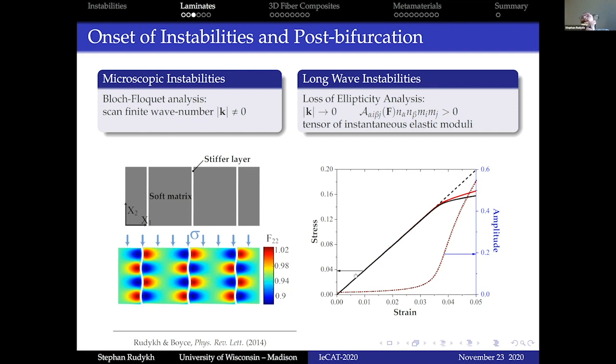and then you can see what happens after the buckling happens, how that develops. And typically what to expect, again on this simple example of the laminate, is that in terms of your stress-strain behavior, upon the critical strain I expect the material to go into a softer mode of deformation. So that's where the material seeks to go into low energy states. And that's where also these imperfections that we put here start to grow very fast. And that is the manifestation of developing instabilities after the onset of buckling.